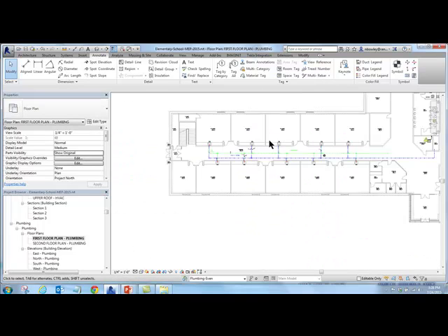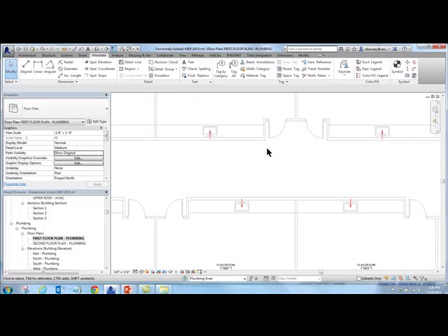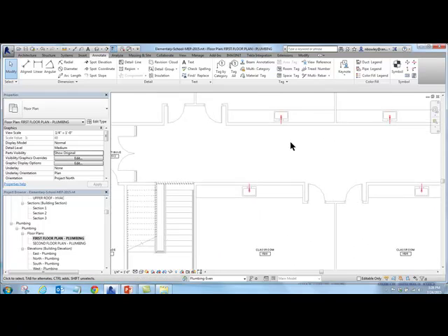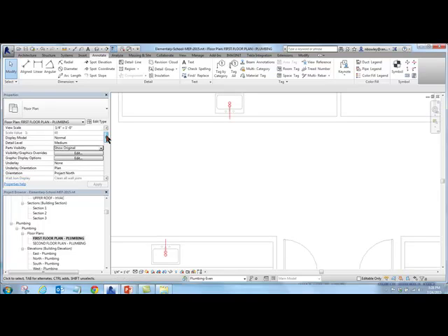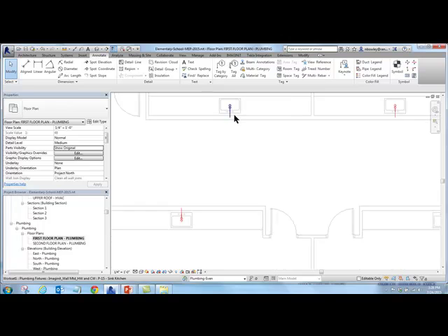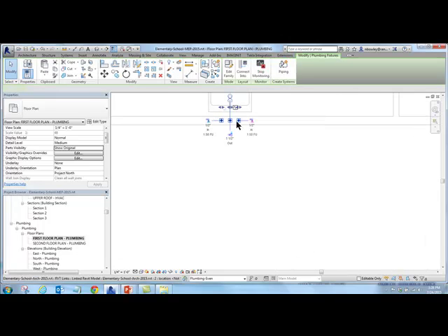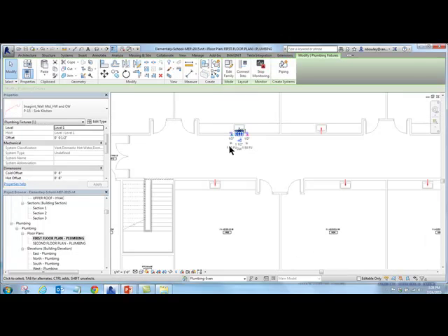And on the first floor, I placed all these fixtures up here earlier. I see a lot of out-of-the-box fixtures where the connectors are on the bottom of the sink, so you have to go down to the wall, up, and that's really too much work. Even if you're trying to model it in more detail, in real life they're not hard piping that anyway. They're going to use a little valve and then a braided line. So I just go straight down the wall and stop right at the fixture, and that's really conducive for auto routing.